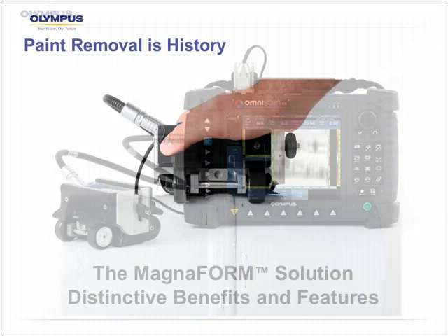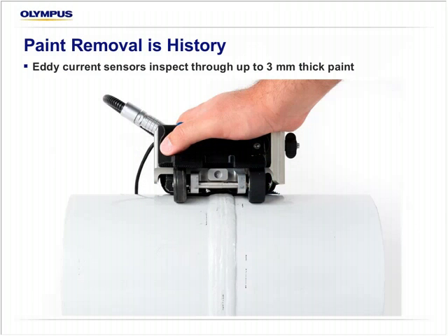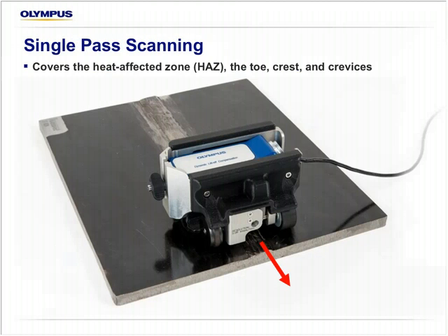inspection. First of all, this sensor or probe or solution can inspect through the paint, so it does not need to be removed. It's been tested heavily on paint thicknesses or shims, because the paint does not affect the results. It's up to 3 millimeters thick without any problems.